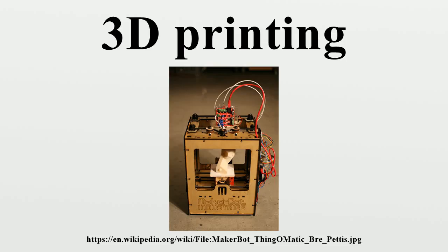There are multiple projects in the open-source community aimed at processing post-consumer plastic waste into filament. These involve machines used to shred and extrude the plastic material into filament. Additionally, fluoropolymers such as PTFE tubing are used in the process due to the material's ability to withstand high temperatures. This ability is especially useful in transferring filaments.